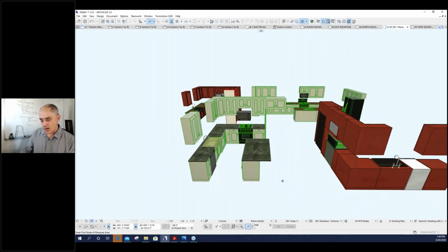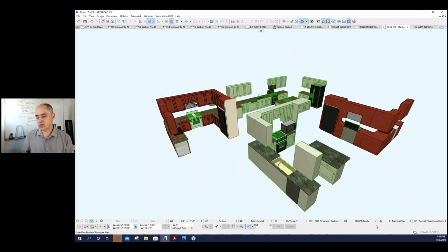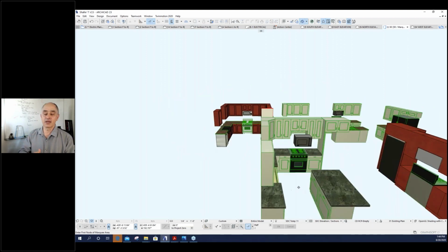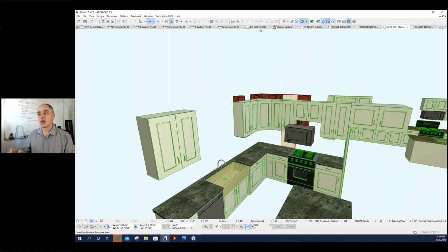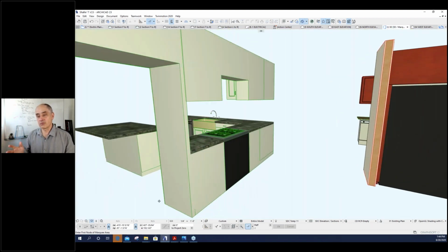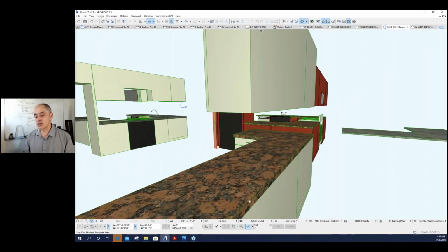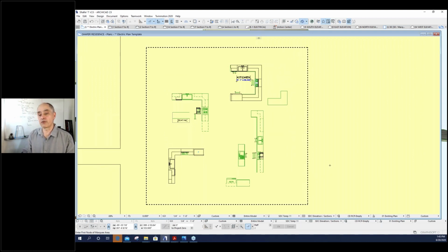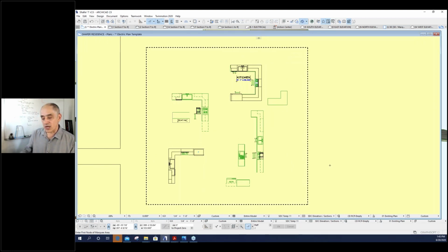Peter Liang, hey Peter, asks: with a custom door panel, does it stretch when the door is resized? If you're making it graphically, like what Roger is doing, it will deform and stretch if you make the door wider. For example, if you make it from 2'6" to 3 feet here in the US, it will just stretch all the parts proportionately. Now, in many cases, that's just fine. And in some cases, that's not okay. You want to keep the side panels exactly the same width as everything else. So what you do there is you create more than one version, and each version is specific per size. Taryn says, that's a nice barn door.